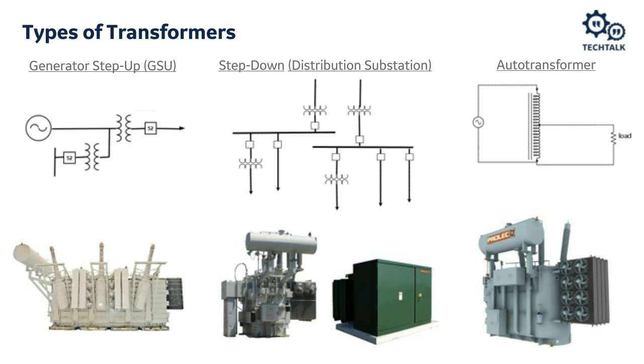With these though, and anything smaller like your single phase pole mount transformers, protection is still important, but it's probably not something you'd put a full-blown transformer relay on. You'd probably rely on other overcurrent backup protection from feeder relays or even just fuses.